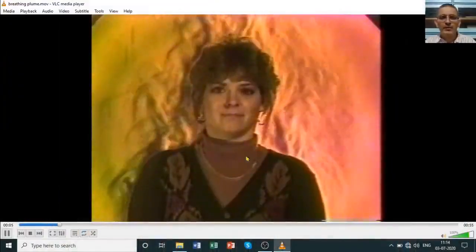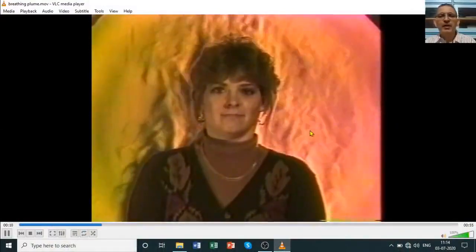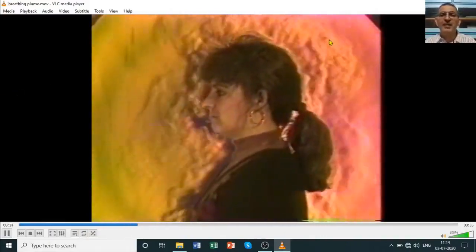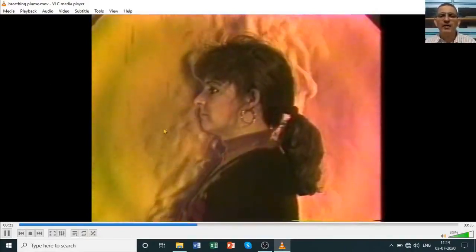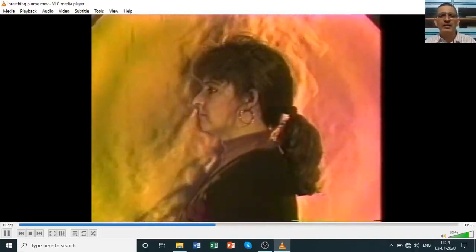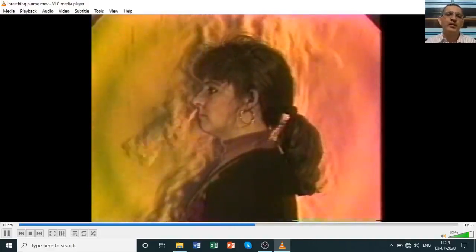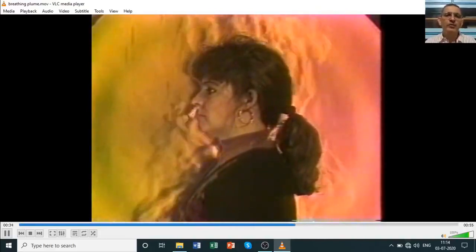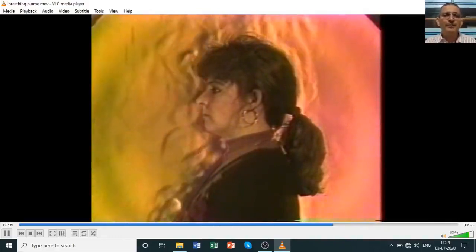Here is one dramatic video. So this person, this is just the thermal convection. The temperature of a human body is 37. Outside, if it is something like 25, 27, there's a natural convection that is set up. And when this person breathes, you can see this plume of air that comes out at a high velocity. It's like a jet of high velocity air. This technique is called shadowgraphy. You can find out more details from the internet, but it just shows you what kind of intense mixing happens even when we are just breathing.